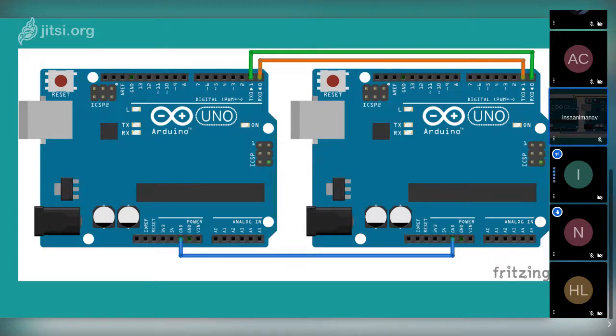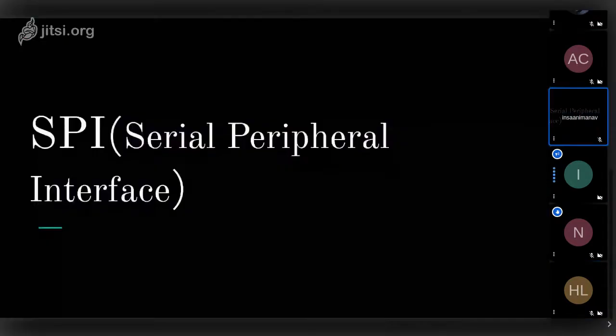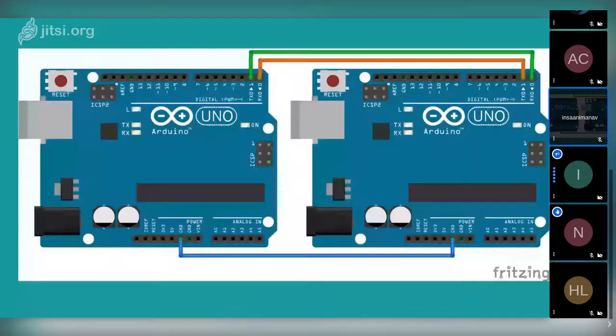So the initial microcontroller sends a 0 volt pulse. The other microcontroller won't know what that means. Right. So we need a common ground between both of these controllers so that we can establish what is 0 and what is 1 for easy communication. So this is what it looks like. Now let's get into the code of how this actually works in case of an Arduino.